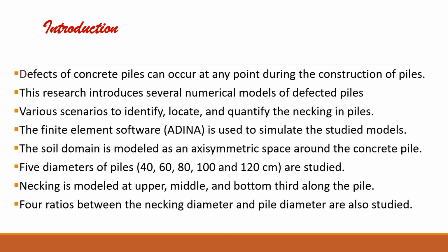Five diameters of piles, 40, 60, 80, 100 and 120 centimeters, are studied. Necking is modeled at the upper, middle and bottom third along the pile. Four ratios between the necking diameter and pile diameter are also studied.